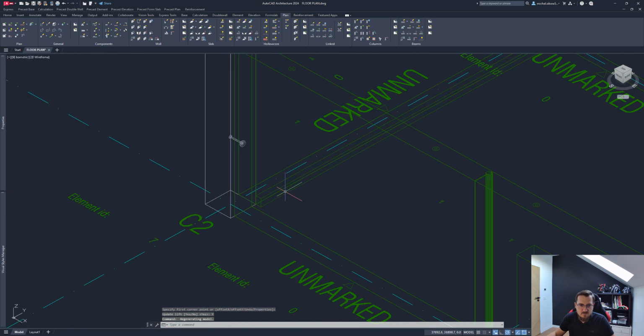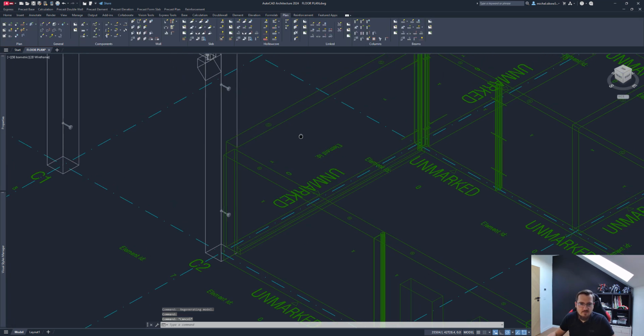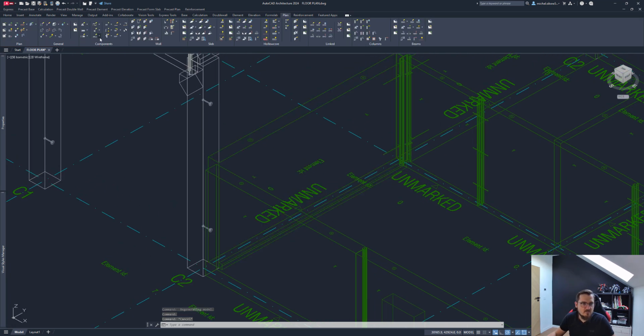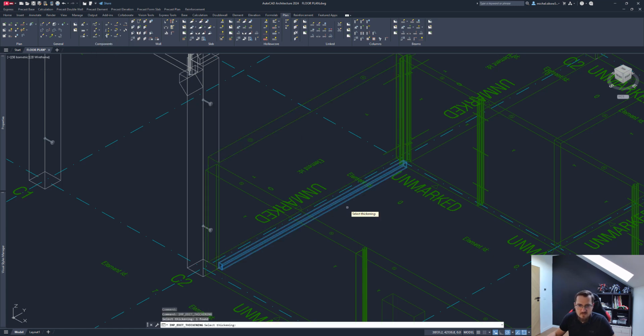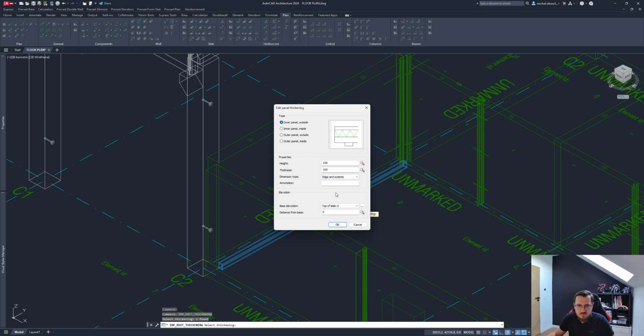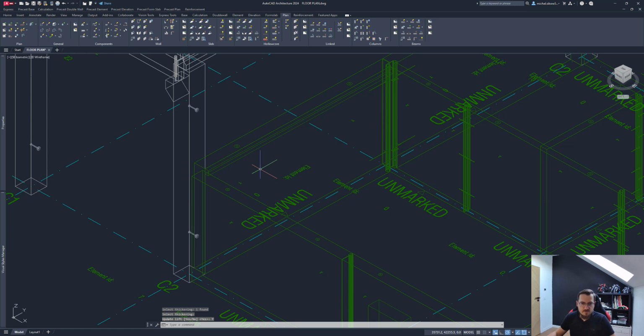Oops. So basically, for some reason, it's placed out on the bottom for me. So nothing bad happening. Let's just edit that. Select thickening. Let's edit that. And for some reason, it didn't choose the proper elevation. So I know my elevation for this should be 250, and that should be good. Let's accept that and update lifts. Yep, that's perfect. That's what I wanted.